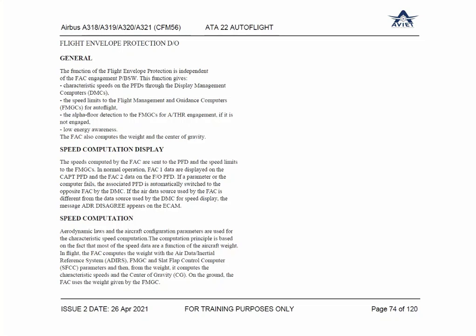Right. So how much fuel is onboard is actually measured by the fuel quantity indicating system. So the remainder is the aircraft normal weight, considering the fluids, hydraulics, aircraft empty weight, or zero fuel weight. That's how they calculate the weight of the aircraft before takeoff and then apply the appropriate thrust. Correct, sir?